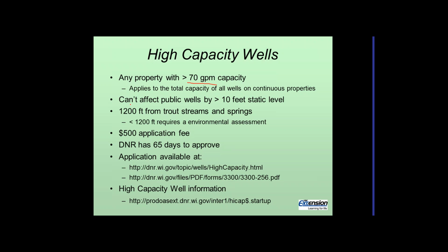When you put a high capacity well in, it can't affect the public water wells by more than 10 static feet, and the DNR will determine this. The setback from trout streams is 1,200 feet. Again, that's a requirement or assessment that the DNR will do.